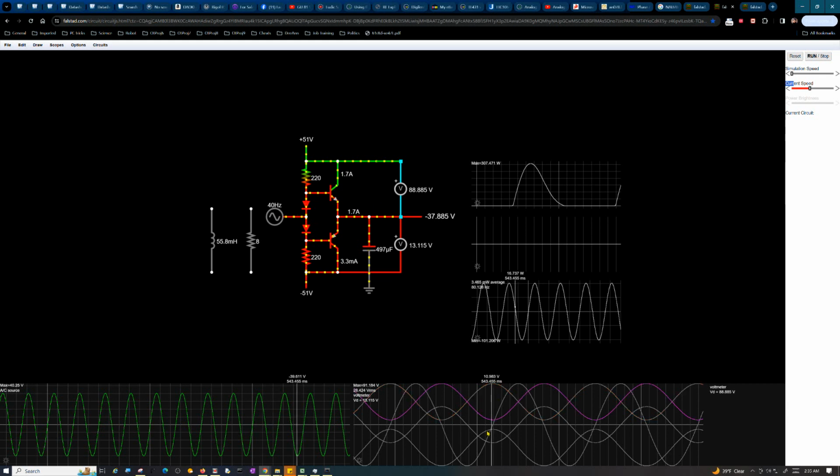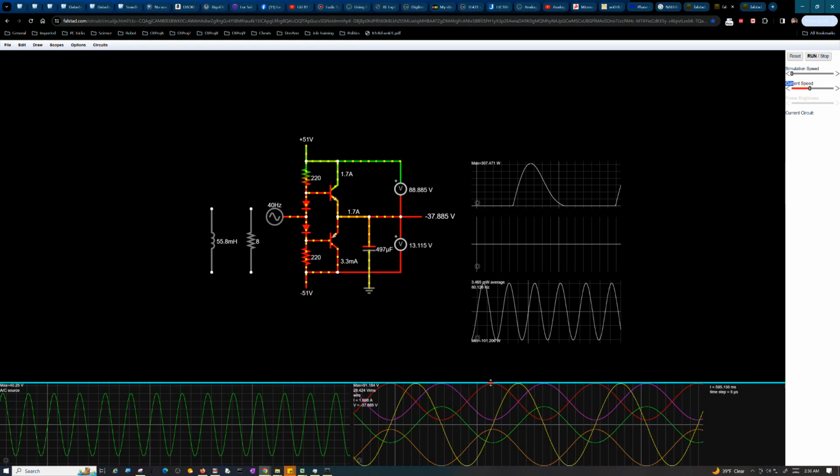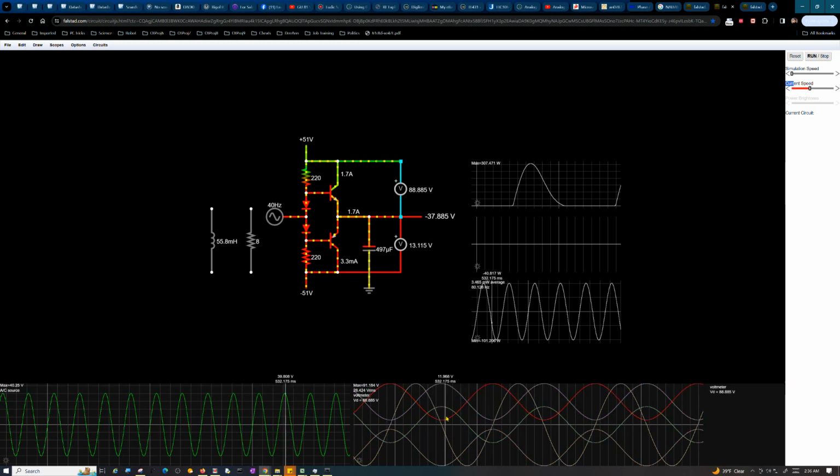The lower transistor is on, which is a lower transistor curve right here, and I'm measuring the actual transistor, where this right here is this meter, and that's that meter, so you can kind of see how out of phase they are, 180 degrees out of phase. But this actually shows you that the closer this waveform gets to the ground line, the zero reference, the more on the transistor is. So like this, the transistor we've been talking about, this peak value is actually when it's fully off. This trough value that's close to ground is when it's fully on. So it gets like 10.8 volts across it.